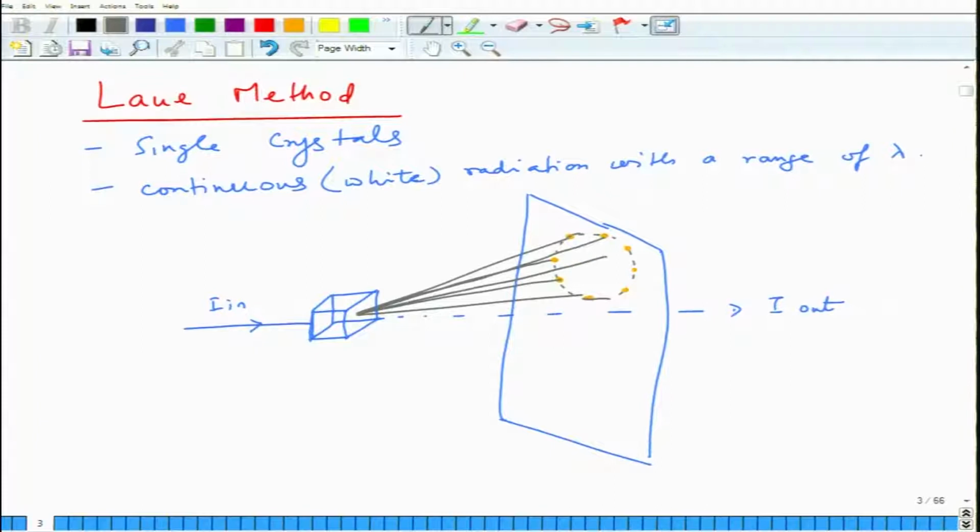It turns out you can prove crystallographically that these planes which will diffract make a sort of cone, and the cone may lie up to the bottom, and the center of the cone is what we call a zone axis. This is the zone axis, and these are all diffraction spots.